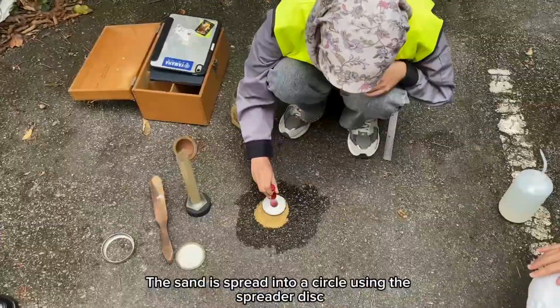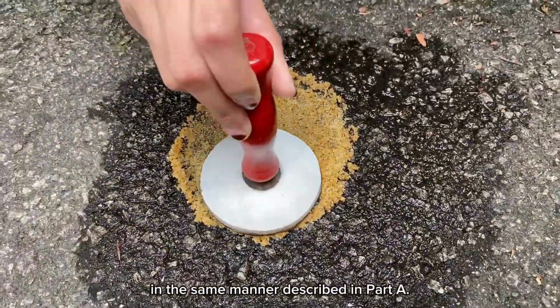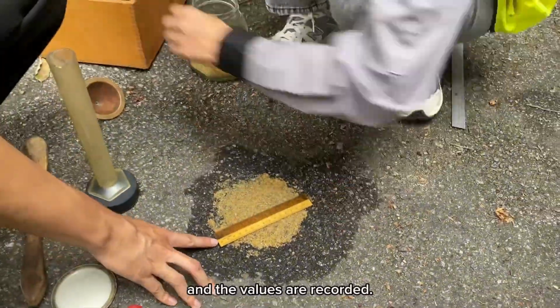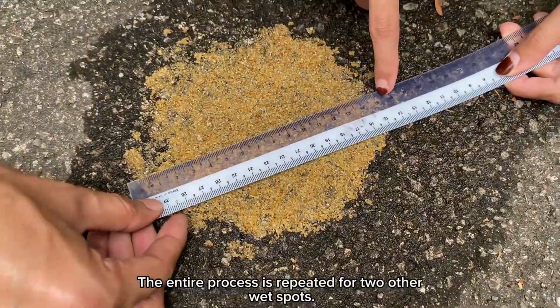The sand is spread into a circle using the spreader disc in the same manner described in Part A. Lastly, the diameter of the wet sand patch is measured in 3 different directions and the values are recorded. The entire process is repeated for 2 other wet spots.